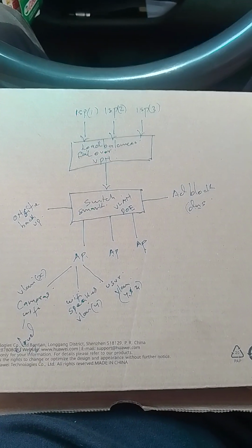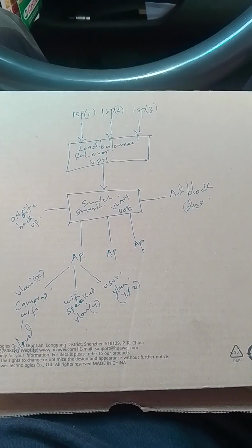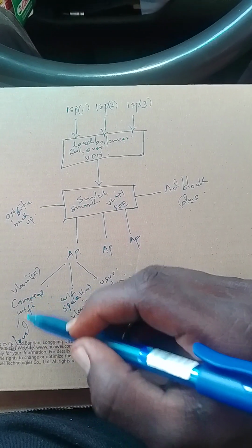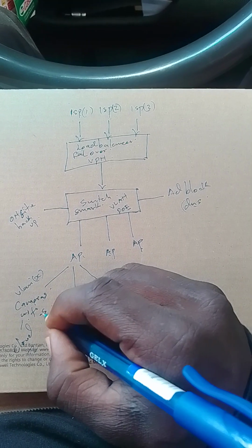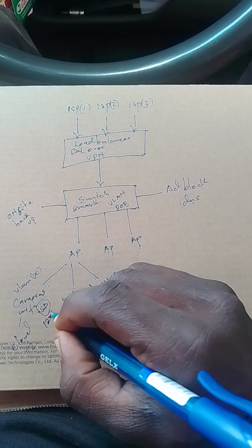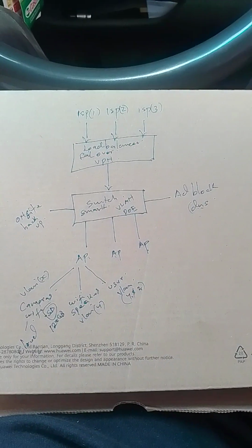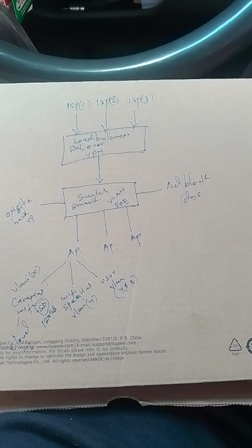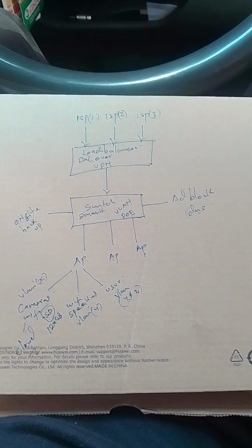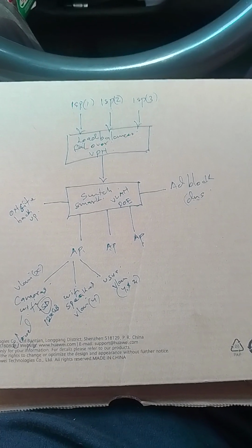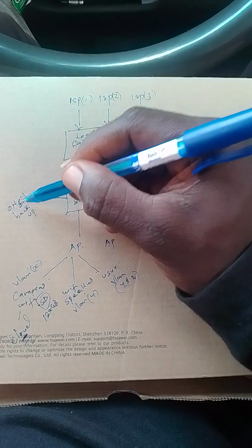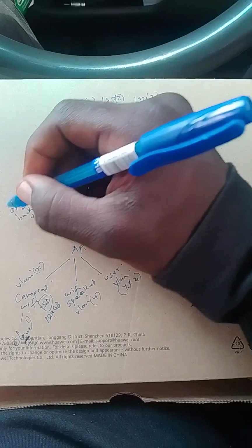Now, a solution that we developed for some of the clients was to have them backup instead of doing a wireless camera, because it has SD on it. It supports up to 128 GB on it. It overrides after a month. It starts to override. That means beyond the month, you won't be able to access anything. So what we do is we introduce a local cloud, which is the on-site backup. So these cameras will back up on this site.